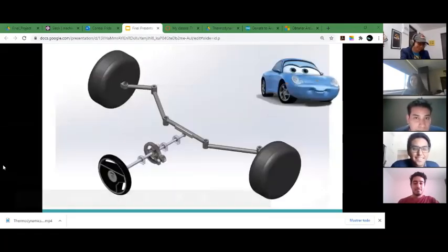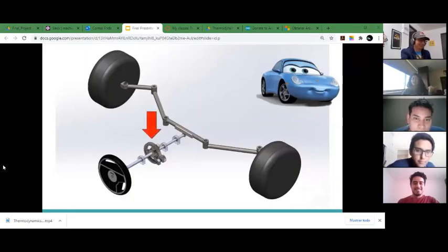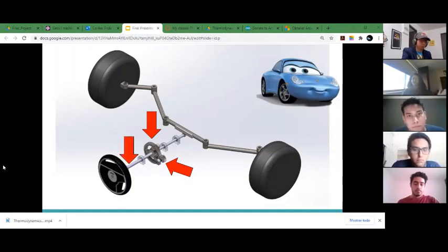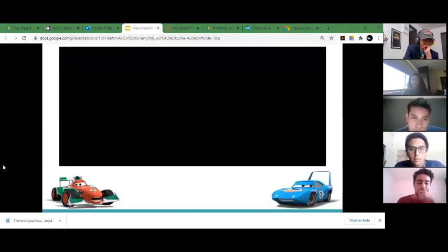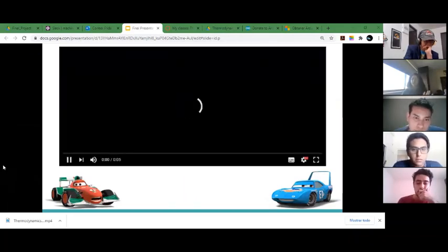Now we will show you our mechanism. First, we have the basic mechanism that contains the gear train, then the motor that assists the driver when turning the steering wheel by acting on the ring gear. Then we have the driver that transmits the power using the sun gear. And finally, the car that moves the pinion with the movements of the mechanism. And now we'll show you a video of the mechanism working.